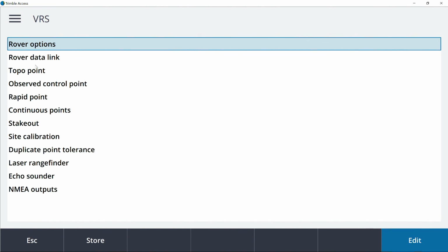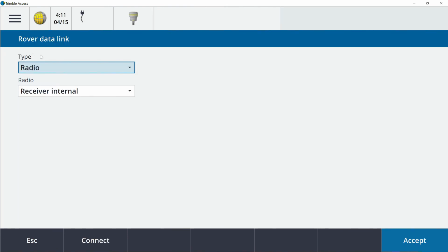So instantly when I do that, you'll notice the base settings in here have disappeared. So we are going to have to then make some additional tweaks in Rover Datalink. So this will be going through an internet connection. Our next page down here, or next setting, is going to be GNSS contact. These are going to be your different dial profiles.